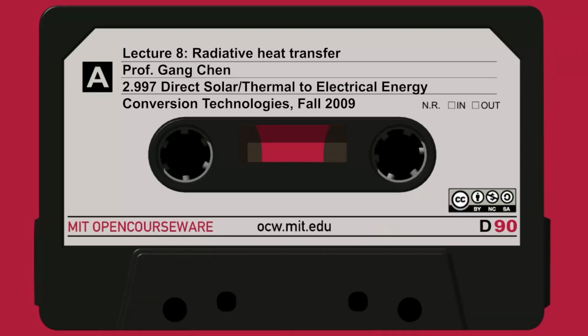Let's look at the Earth and Sun. Because they are so far apart, essentially I can treat them as very small surfaces relative to each other, so it's a dA. And rather than look at the curvature, because each point will have a different angle perpendicular to the surface, you can just treat this as a disk, and this as a disk.